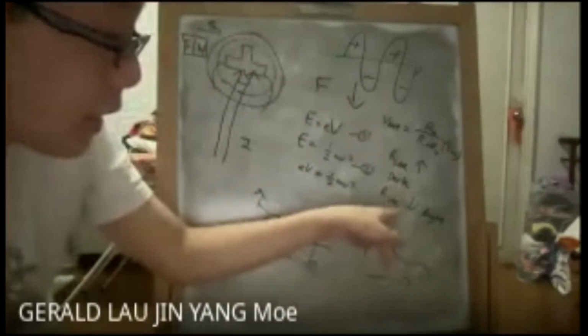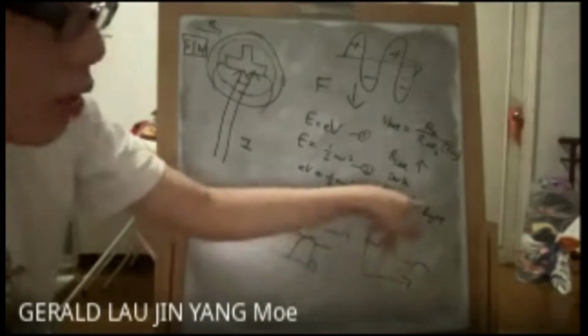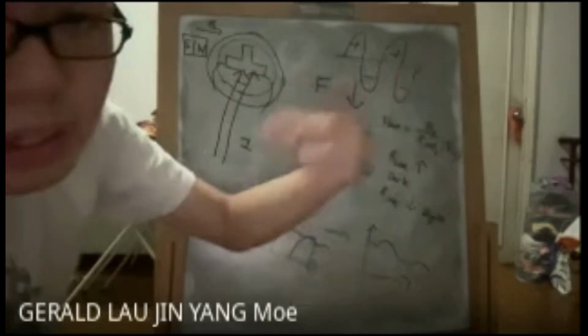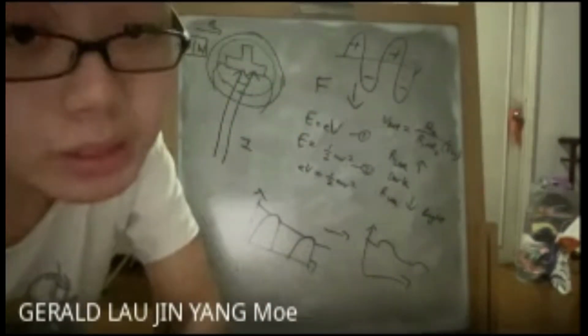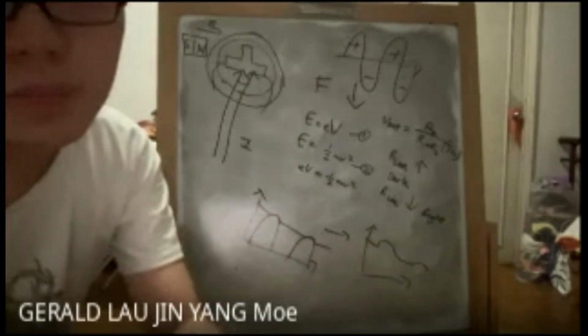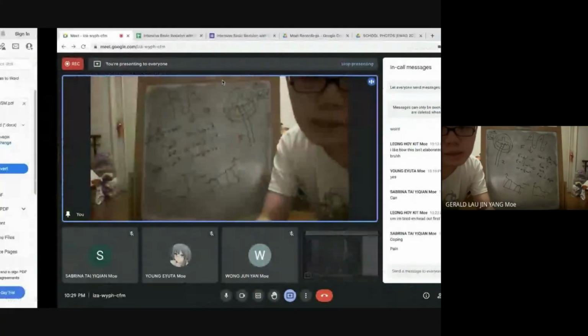But when it's daytime, bright condition, resistance is low. Resistance low, voltage low. So it will not activate the current. There's no base current flowing, so the bulb does not light up. This circuit is used in automatic street lights. Okay? Right? Yes, it's plain.